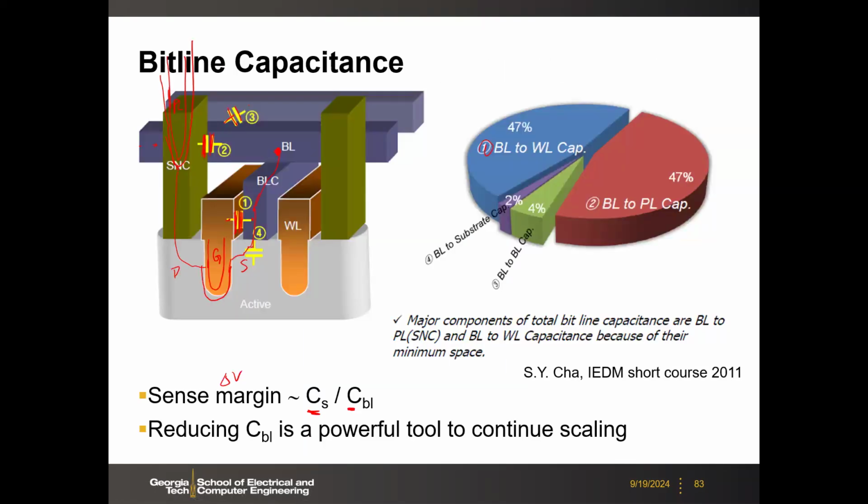So one solution to that is here. You see the capacitance depends on the dielectric between those two plates, right? For CS, you want high K dielectric in between. Then for those parasitic capacitances, you always prefer low K, right? Low K dielectric to reduce those capacitances like 1 and 2 here. If you can fill the isolation with low K material, that will help.